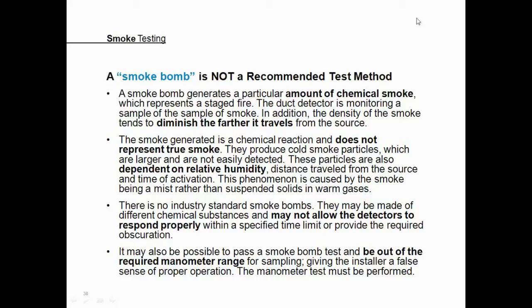Furthermore, one of the reasons that smoke bombs are not recommended is that there is no standard set aside for producing them, and they may not all be creating smoke in the same manner and may not allow detectors to respond properly. Also, it may be possible to pass a smoke bomb test and actually be out of the required range for sampling smoke with the detector, and this would then give you a false sense of security. So overall, we do not recommend testing with a smoke bomb. We recommend doing one of the other testing methods that we've spoken about already.